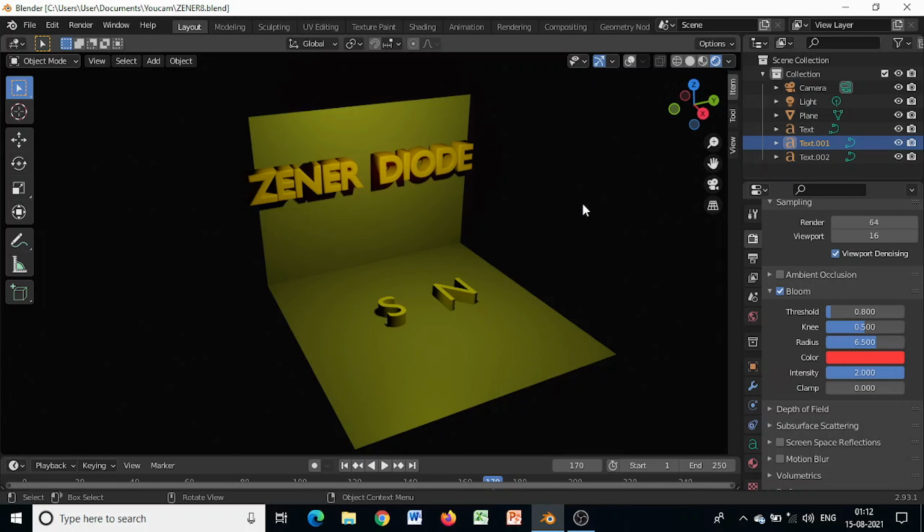In this video, if you look at the Zener diode characteristics, you will see current is increasing, but voltage across Zener is constant at Zener breakdown voltage. For this property of Zener diode, it is used as voltage regulator. Now, what is Zener diode and what is Zener breakdown?